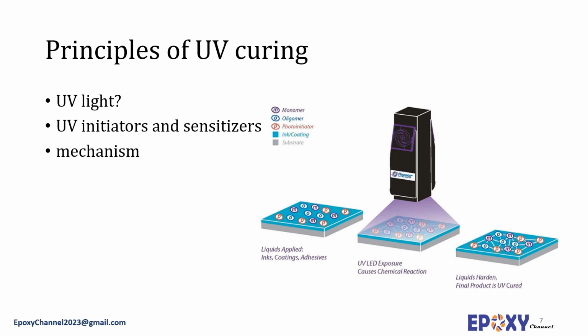By this strategy, the inhibitory effect of the oxygen at the surface and upper layers will be compensated. Photoinitiators and sometimes photosensitizers are used to compensate for the lower energy density of UV light, which is initially inadequate for the polymerization reaction. The UV absorber or sensitizer is transformed into excited sites after absorbing the UV light, which subsequently forms free radicals by cleaving of the bonds or by the adding of the hydrogen atoms.